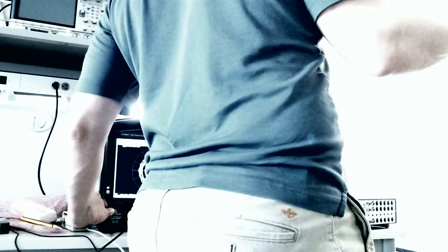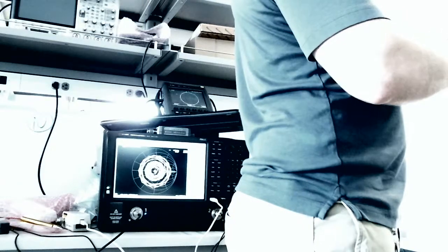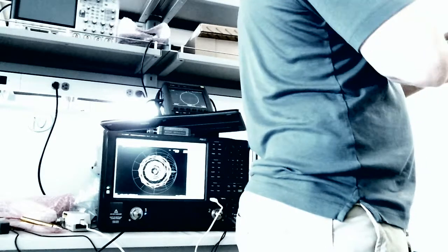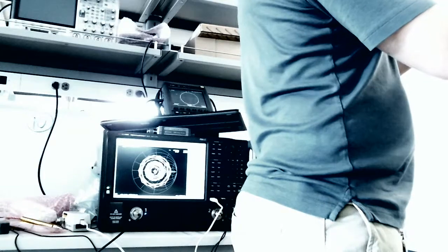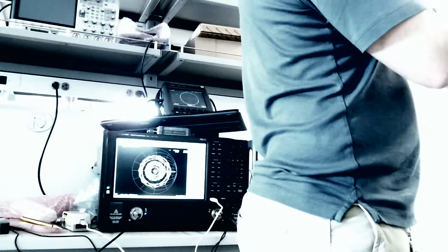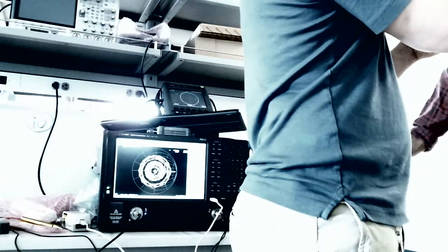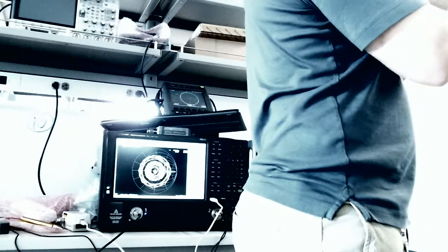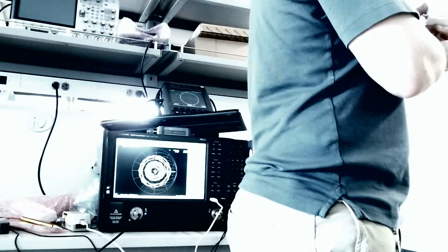Remember when I said the limitation is really that -40, you can't get any better? It's because if you take a look at the coupled port, for example, if I send a signal here, this is the load that I'm measuring right on the out. I'm going to have some leakage on the out, even though this is going to be my reference signal that I want in the coupled port here, but I'm going to get some undesired leakage. And the ratio of that leakage versus the loss in the coupled arm, the coupling factor here, is what's going to give me the limitation as to how small of a signal I can measure.